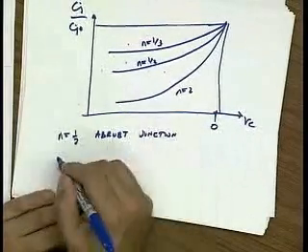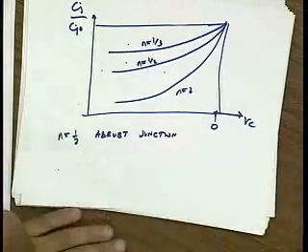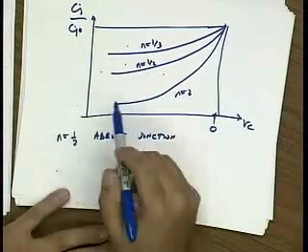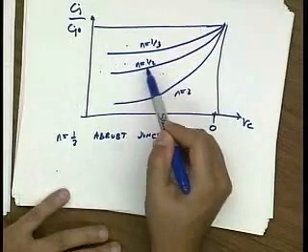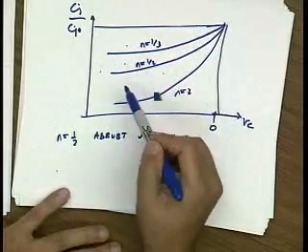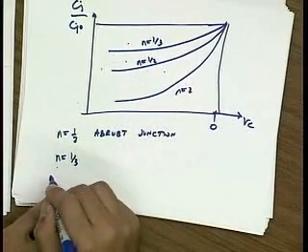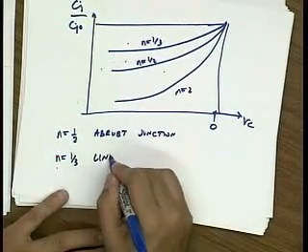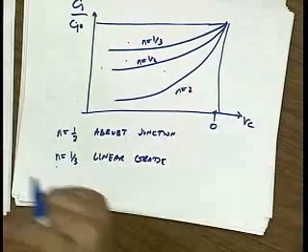It's much more likely that there's going to be some kind of actual gradient, right? Not an infinite gradient. And that gradient will lead to a different kind of slope. And that's why in SPICE, N is never equal to 1/2. It's always something like 0.3 or 0.4. In fact, if you do N equals 1/3, that corresponds to a linear grade. In other words, the doping changes linearly from one side of the junction to the other.